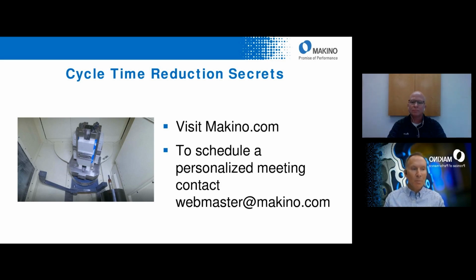multi-axis positioning, that is one of the things that I know you said customers usually can benefit from. Yeah, talking about low-hanging fruit, that's a parameter change. It's a FANUC parameter, as I mentioned, the 5001. You change that parameter, and you can, especially on the G43, the tool length compensation line, add multi-axis positioning all on that same line.